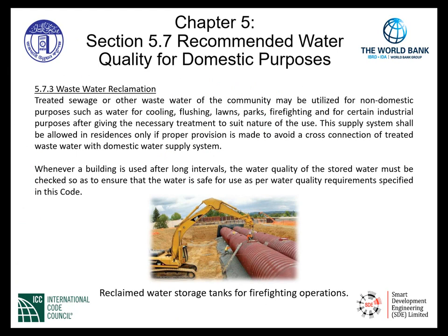We can also use water and reclaim the water. Section 5.7.3 allows wastewater reclamation. Treated sewage or other wastewater of the community may be utilized for non-domestic purposes, such as water for cooling, flushing, lawns, parks, firefighting, and for certain industrial purposes, after giving the necessary treatment to suit the nature of the use. Very important statement there. Treatment to suit the nature of the use.